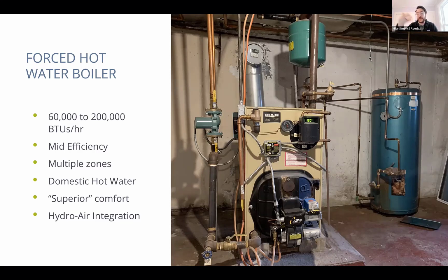It condenses somewhere in the basement or along your walls and drops back down into the boiler, and it never actually makes its way into the radiators. But with forced hot water, pipe insulation is a really great idea because instead of heating the spaces that you're not using, all of that energy inside of the pipe could be heating the spaces that you do want to heat. So pipe insulation is always a very, very good idea. Thanks for the comment, Nicole.